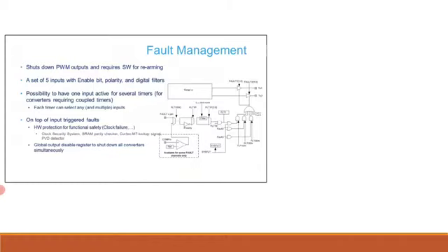For converters requiring multiple synchronized outputs, on the other hand, multiple fault inputs can be merged to protect a single timing unit. The faults come from several sources: the digital inputs, the built-in comparators for some channels only, and the system errors.